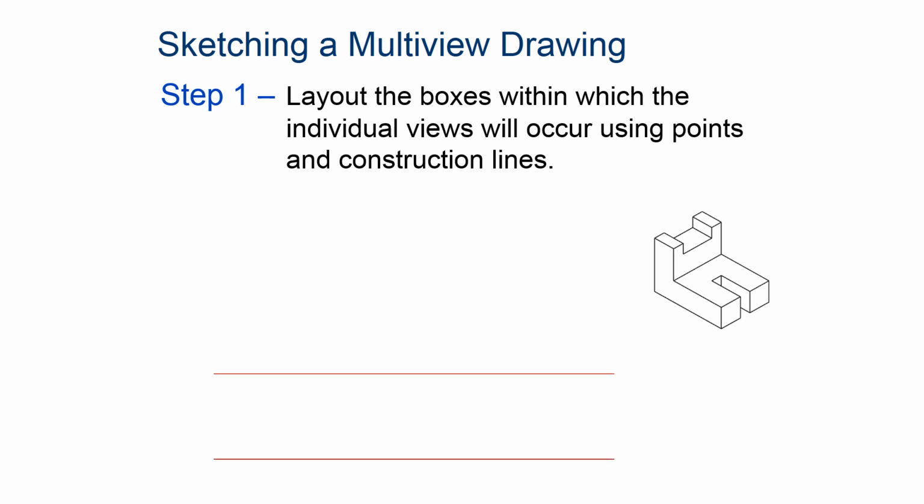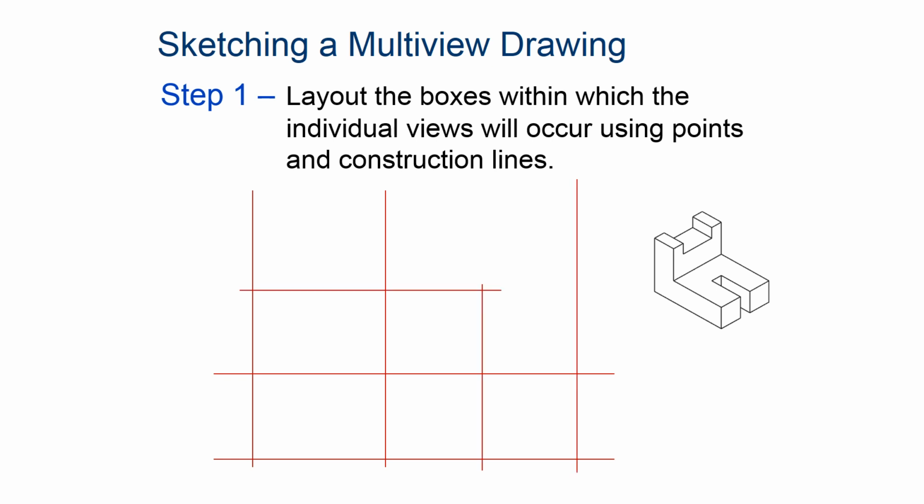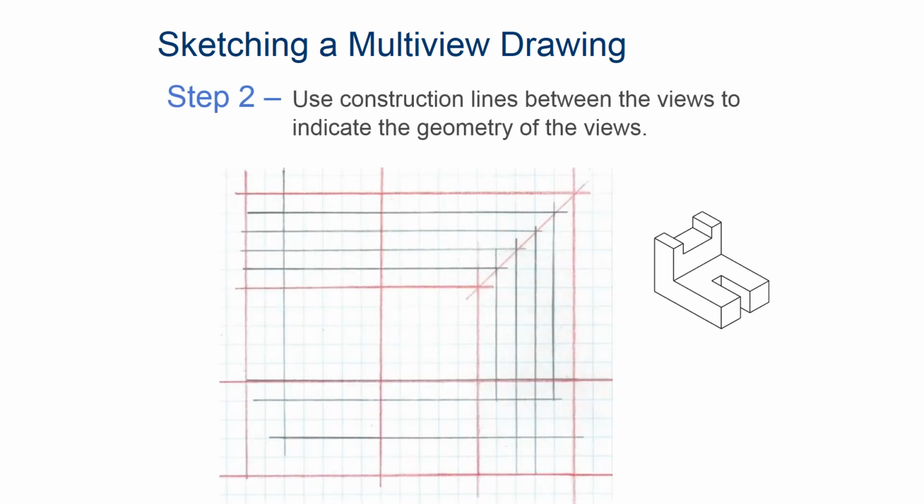So we'll lay in our construction lines here. Here's top, here's the height, there's the width. Then we're going to move over a little bit and lay in the depth. There should be a 45 degree line. That line should probably come in first to show that you project up and then over. All right, now we have the three views, top, front, and side. So that's number one. There's your top, and there's your front, and there's your side. You saw the three views.